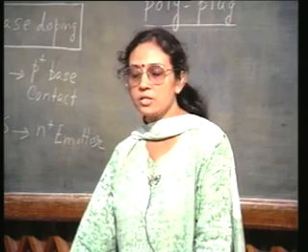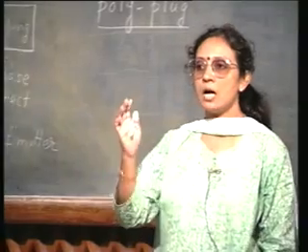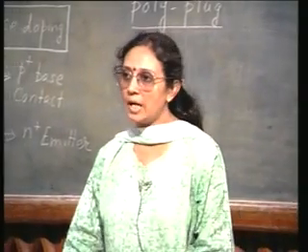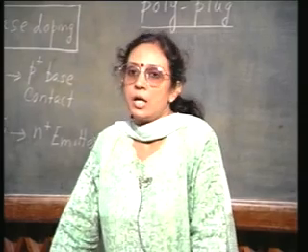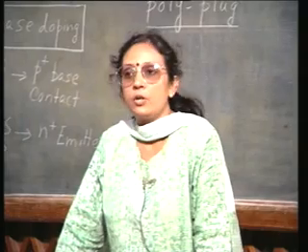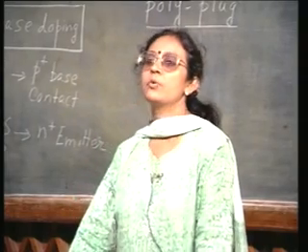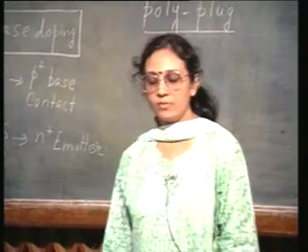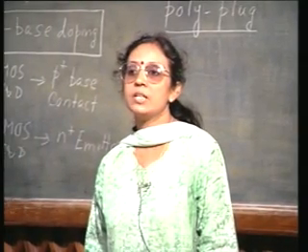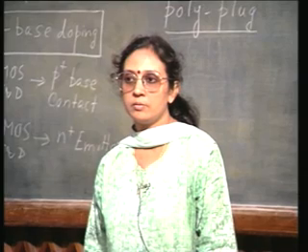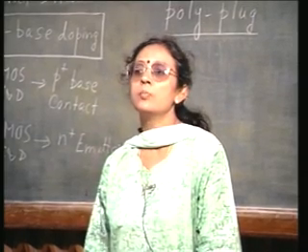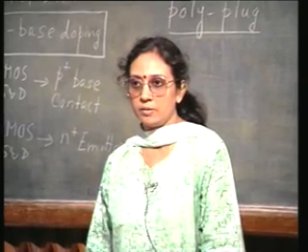So, what happened essentially? The trench is isolating two regions of the semiconductor by means of this undoped poly sealed on all sides by the oxide. Now, suppose you have a trench etched and fill it up not with undoped poly, but with heavily doped poly, then what you have is called a poly plug, right.